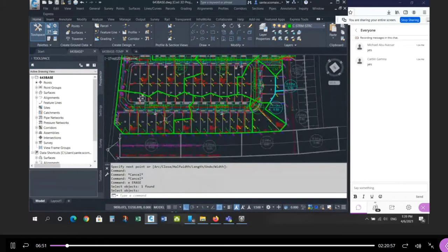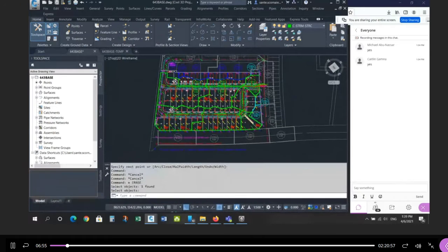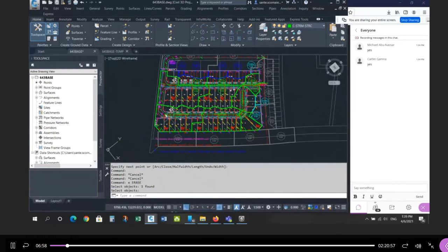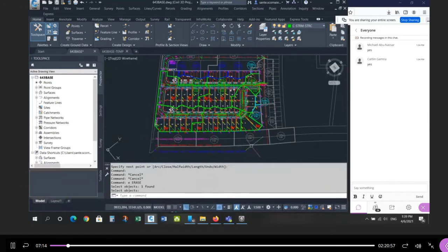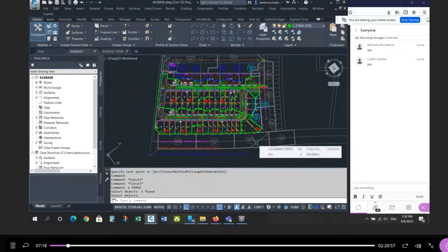So when we did that, maybe these 2 or 3 pipes got a little bit bigger, and it may have influenced the whole system all the way to the end, because we're adding more flow to this entire leg of sewer. It doesn't affect these 2 pipes, but it would affect this little short one, 3, 4, and the last couple pipes coming out. So that was a design revision when we realized I can't take these backyards to this road out here. It doesn't work. There's not enough capacity in this sewer system here.